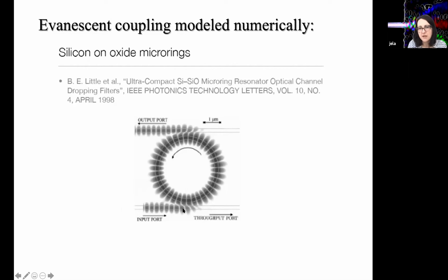And of course, this depends on the design of the system and overlap within the waveguides and the rings, so you have to be careful, but people can design the system to have nearly perfect efficiency of transmission to a particular output port. So this is your input port, this is your output port. There is nothing going on to the throughput port and also this additional fourth port of the system for the right design.